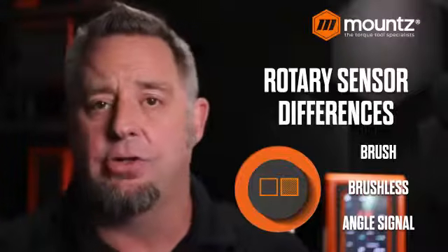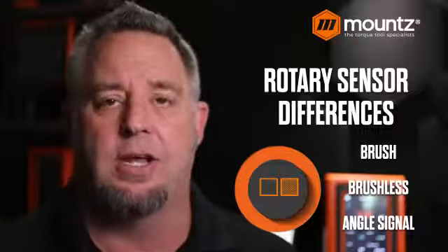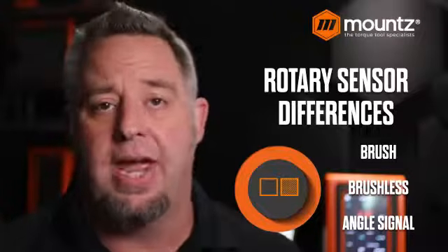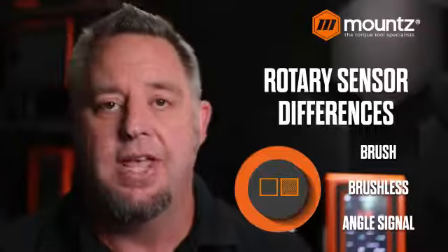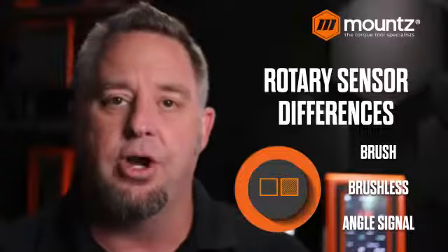And then we also have angle transducers that basically will signal at every degree of rotation. So they are built with an angle encoder in there. And so we use those with the torque analyzer to do measurements of different torque and angle type of settings. This can also be useful if we are doing auditing where you want to look at testing a fastener after it has been torqued.